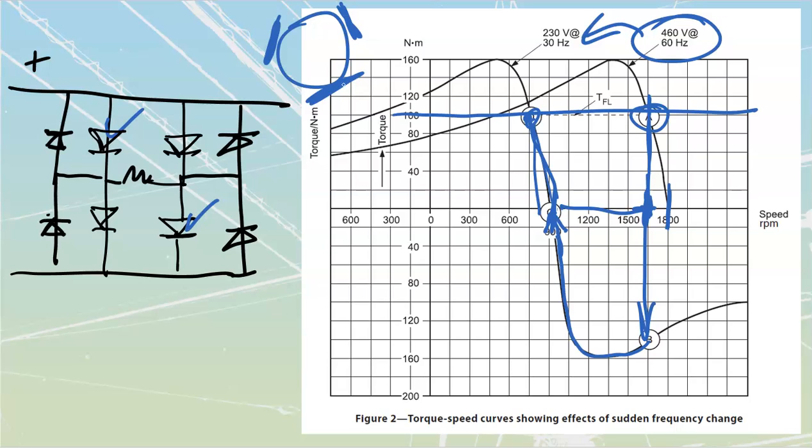For reversing AC motors attached to these drives, we don't have to interchange any lines. The drive itself is just going to change the sequence that it runs. In a lot of cases our drives are going to have a low voltage bus. We're going to have our three main terminals at the bottom, U, V, W, as well as our line 1, line 2, line 3. Those are going to be the main ones.